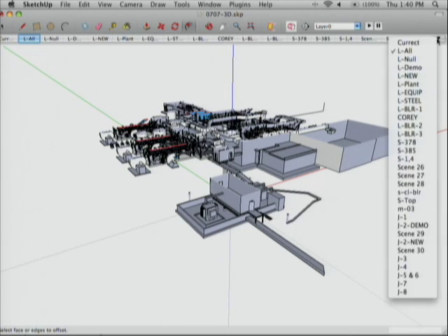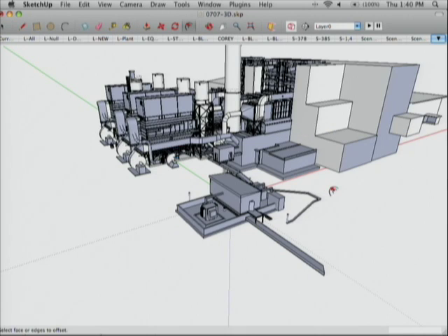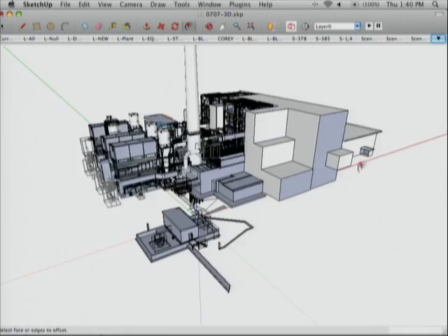I'm going to see if I have a section. Another little tip on sections is just put a section up high above your model and flip to that. It's a lot less trouble than turning the section cuts off all the time. Because you'll think you've gone to a section tab and you'll think it's not working. And it's just because you turned off the section toggle.